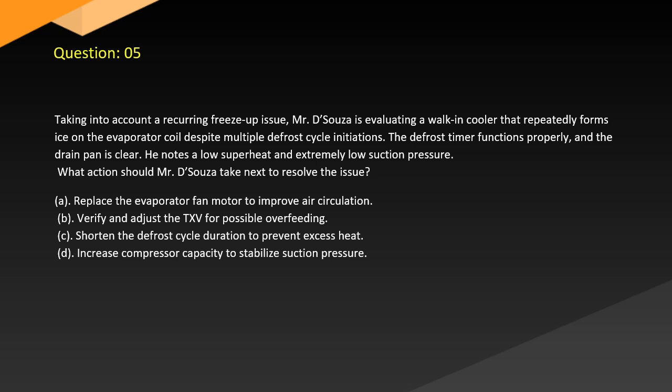Question 5. Taking into account a recurring freeze-up issue, Mr. D'Souza is evaluating a walk-in cooler that repeatedly forms ice on the evaporator coil despite multiple defrost cycle initiations. The defrost timer functions properly, and the drain pan is clear. He notes low superheat and extremely low suction pressure. What action should Mr. D'Souza take next to resolve the issue?